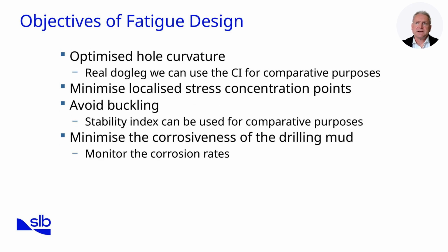The objective of fatigue design is not simply to prevent every possible failure, but to manage risks so that the drill string can perform reliably within the expected life of a well. The first aim is to optimize hole curvature by planning realistic doglegs that the string can safely tolerate. We reduce unnecessary stress exposure. Closely linked to this is the goal of minimizing localized stress concentration points, such as sharp changes in geometry at tool joints or poor machining at thread roots.